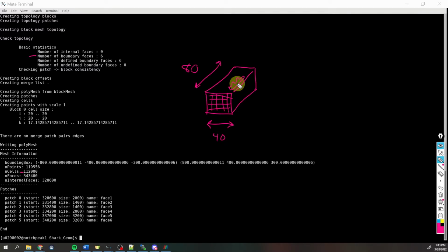What it does is it takes those cube elements that are right near the surface and it slices them to conform them to the surface of the skin. This is equivalent to the Boolean process that you did in ANSYS, so that we get rid of everything that's inside of the shark and we're just left with this exterior volume.